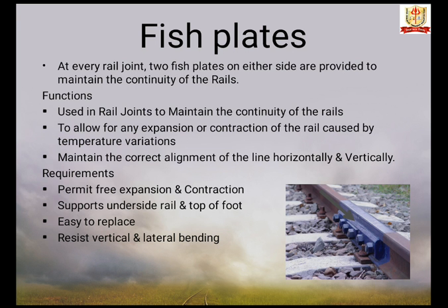Fish plate is made of mild steel. Mild steel flat, 20 mm thick, is used for the fish plates. Each fish plate is usually 456 mm long, provided with four holes of 32 mm diameter at 114 mm center to center. The fish plates are rolled to a section to fit in between the head and foot of the rail.